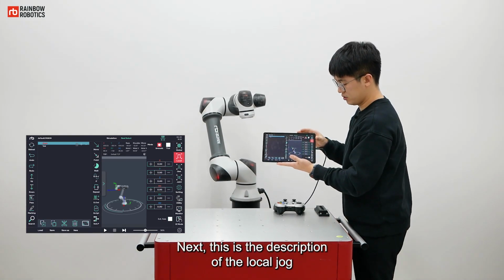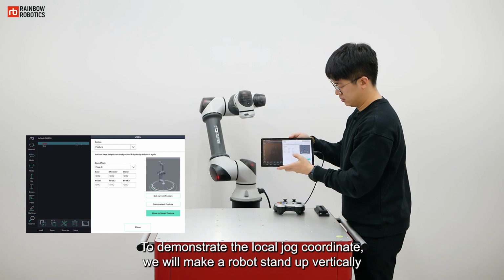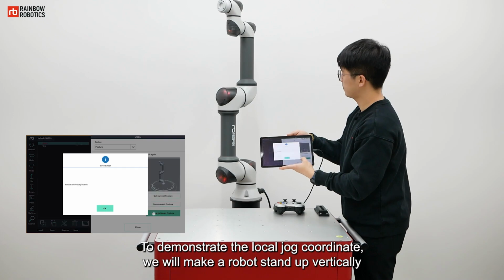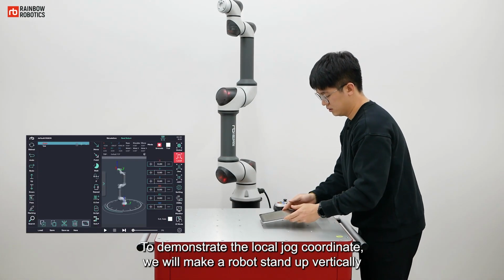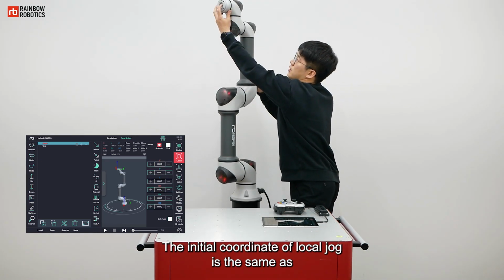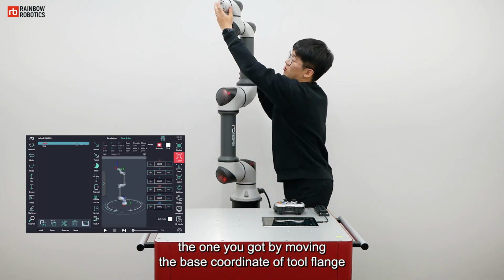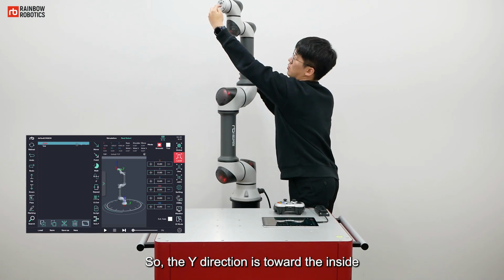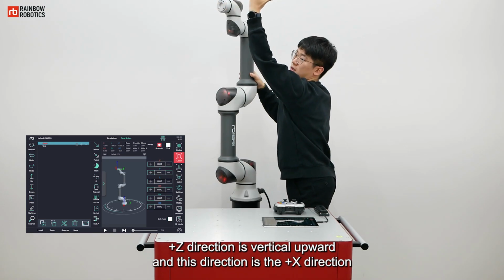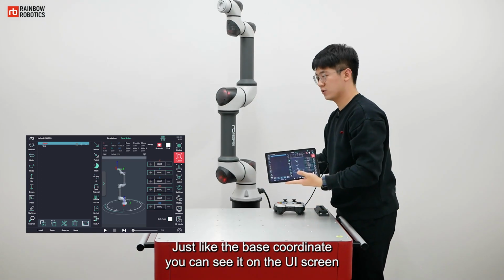Next, this is the description of the local jog. To demonstrate the local jog coordinate, we will make the robot stand up vertically. The initial coordinate of the local jog is the same as the one you got by moving the base coordinate of the tool flange. So, the Y direction is toward the inside. Plus Z direction is vertical upward, and this direction is the plus X direction. Just like the base coordinate, you can see it on the UI screen.